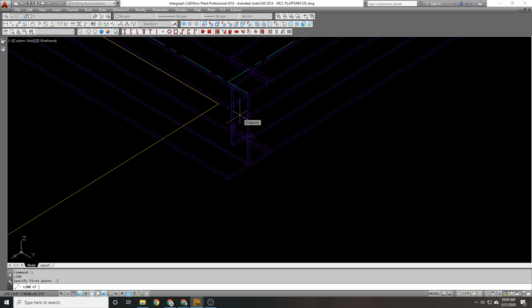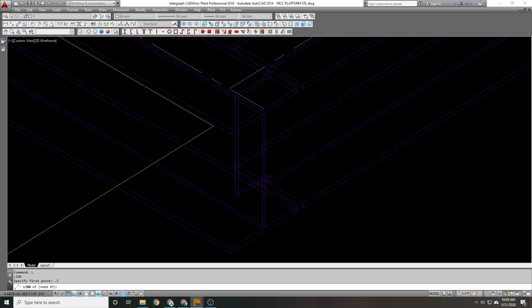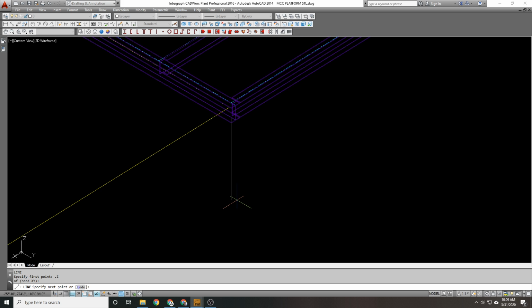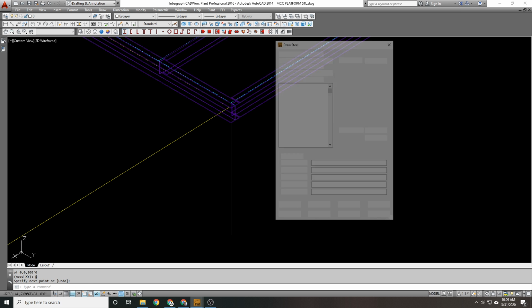I'm going to say .z, so I start here. My x and y starts here. So I'm going to start here, and I'm going to take this down to a .z of, I think my elevation will be starting at, let's put 108.6. Actually, it's 0, 0. I put insert on. Oops. 0, 0, comma 108'6". So this line, we'll say at for the xy. This line will go down to here. Now I'm going to put my column in place.